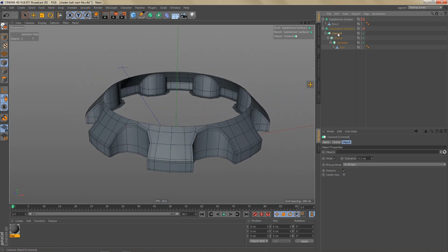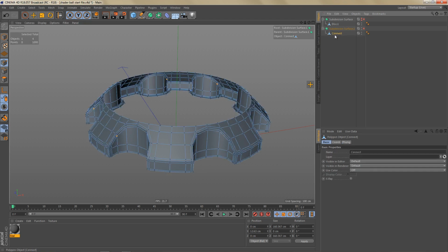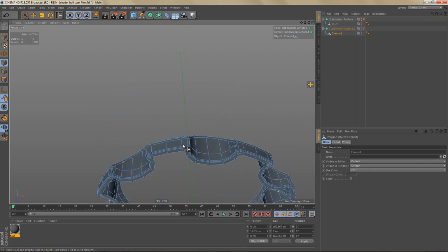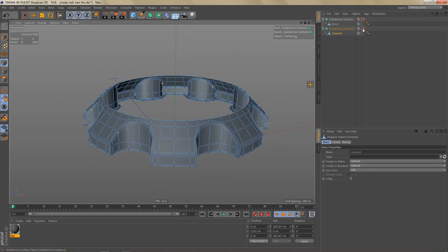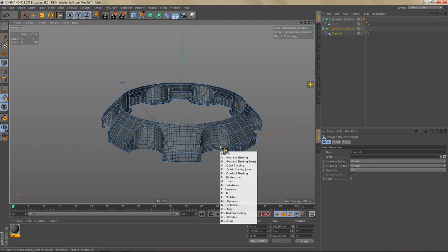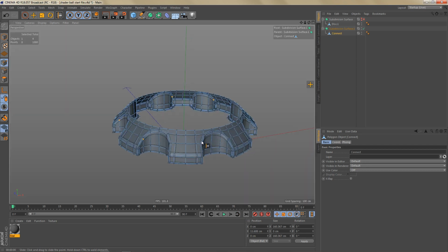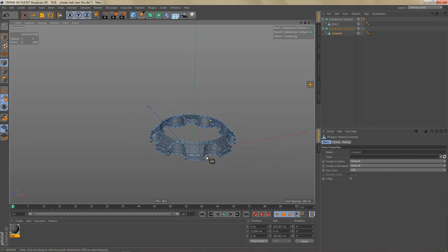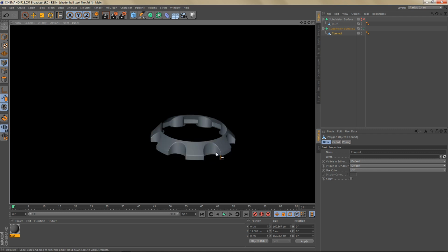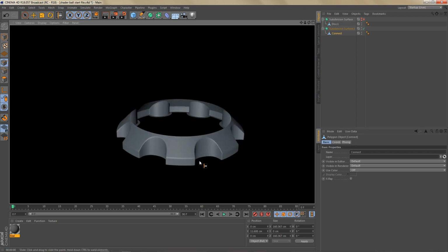Now we can make the connect object editable. It will also weld the points at the seams. And if I subdivide this, we're getting a pretty nice looking result. And you can see the edges up here are a little bit softer. But like I said before, in this case I've decided to leave it as it is. It's not looking too bad, and if you zoom out, I think some of the edges are almost a bit too sharp for my taste. But overall it's looking pretty good.